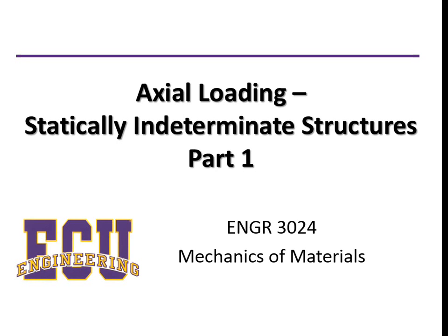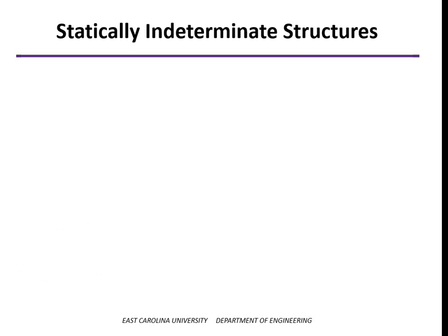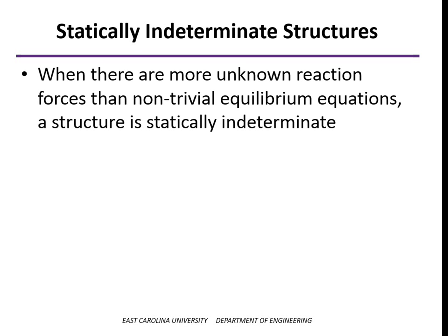In this video, we're going to take a look at a statically indeterminate problem involving our equations for axial loading. To start out with, let's define what a statically indeterminate structure is. We know that we can solve an equilibrium problem with statics if we have the same number of reaction forces as we have equilibrium equations, or to be more specific, non-trivial equilibrium equations. But if we have too many unknowns, then our structure is statically indeterminate.